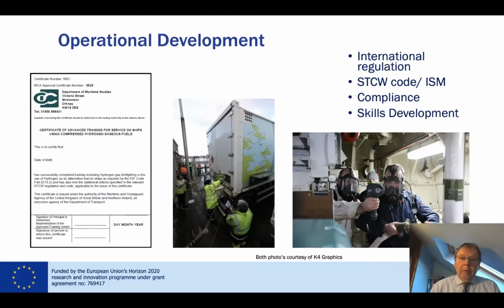Also in that course, there's a firefighting element which deviates from the normal training that you would get, as in you see the guys on the right-hand picture there using a thermal image camera with a hose and also breathing apparatus, looking to detect and isolate and cool rather than extinguish hydrogen. That's something that just changes everything.